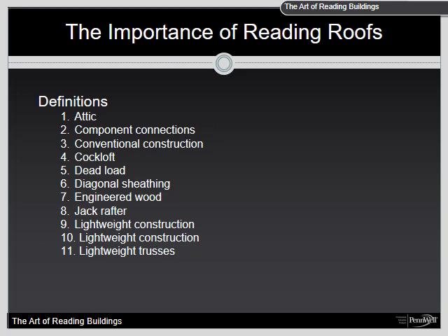Dead load. The weight of the building itself and anything permanently attached to the building. Diagonal sheathing. This is a series of 1 by 6 inch boards that run at a 45-degree angle from the exterior walls to the primary structural members and provide increasing structural stability as they cross more roof structural members. This style of sheeting was favored after the 1930s.